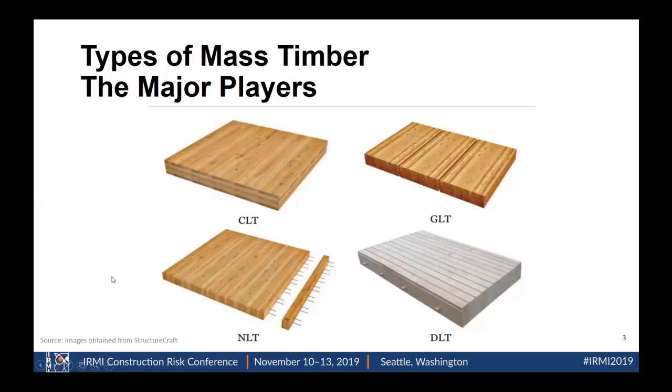There's DLT, which is dowel laminated timber, and the dowels actually swell and hold the 2xs, which are on their side, similar to NLT, in place. We used CLT for our job in Northwest Arkansas. CLT could be used on a horizontal surface, like your decks, or on vertical surfaces too, to create your elevator cores, do your exterior walls, anything that you would want to use it for.